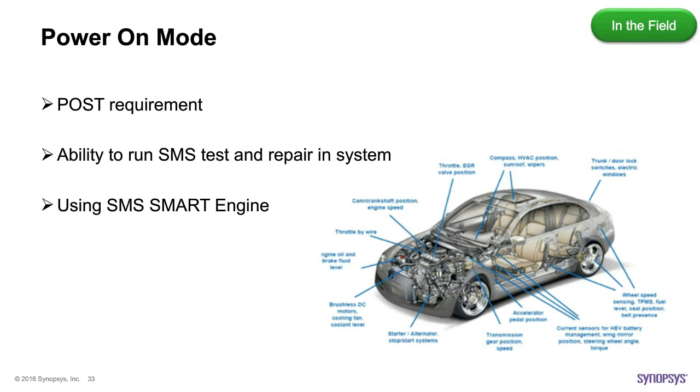Now, the star memory system, while we invested in the IP to test the chip upon manufacturing, that same investment can be utilized in the field as well, of course, with slightly different conditions. Here, the repair has to be done much faster because when you power on, you have very limited time to bring the system to its normal situation. Therefore, you need to have parallel repairing, and we have a nice advanced repair capability that we built into this system. The self-test itself needs to be done again in a fast way.